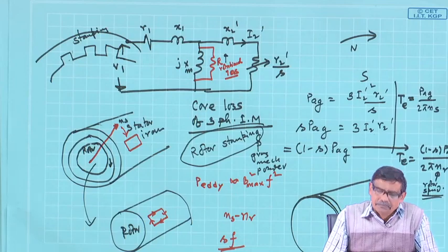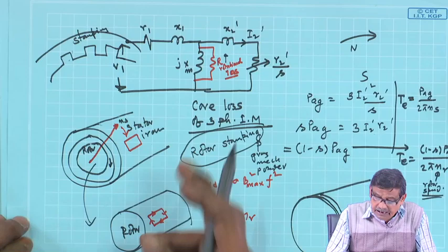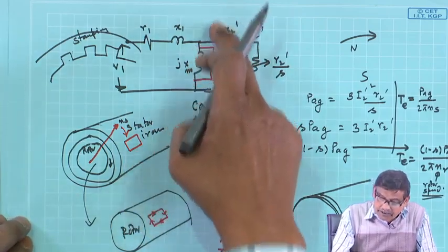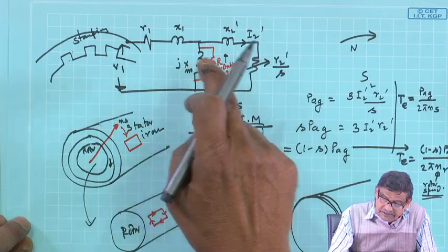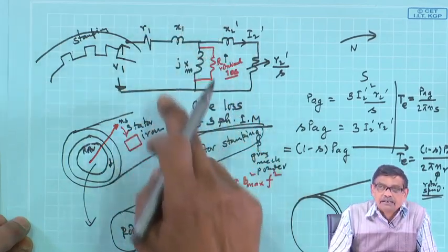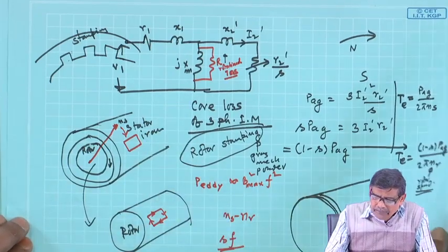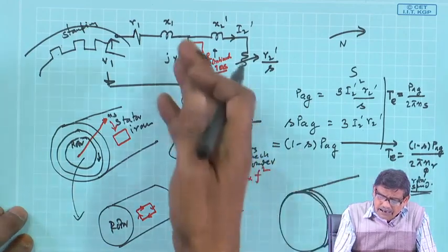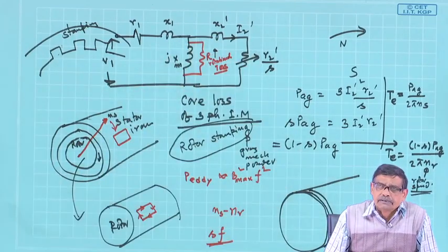It will become slightly more involved in calculations, because you have to calculate R Thevenin, which will be this resistance, this Xm and this R1 jX1 in parallel. So, calculations will be slightly higher, but if it is neglected, because what happens, magnetizing current is much higher than the core loss component of current.